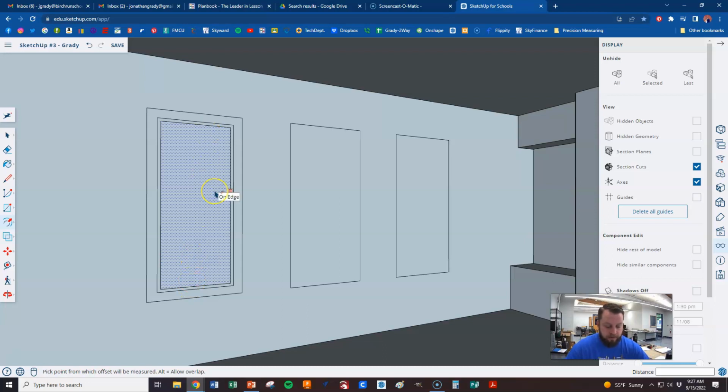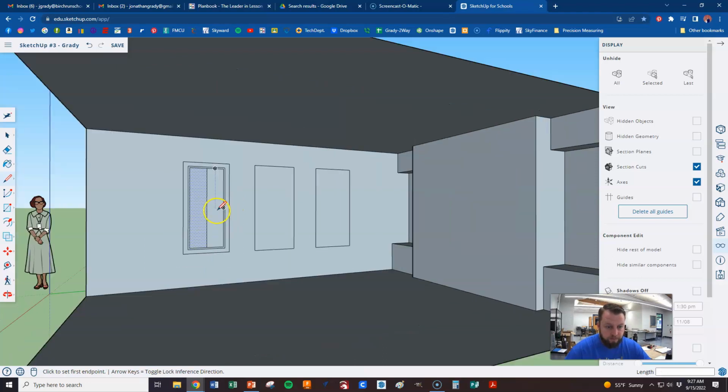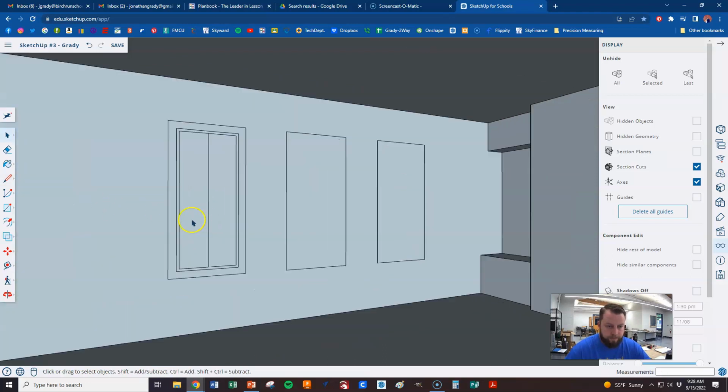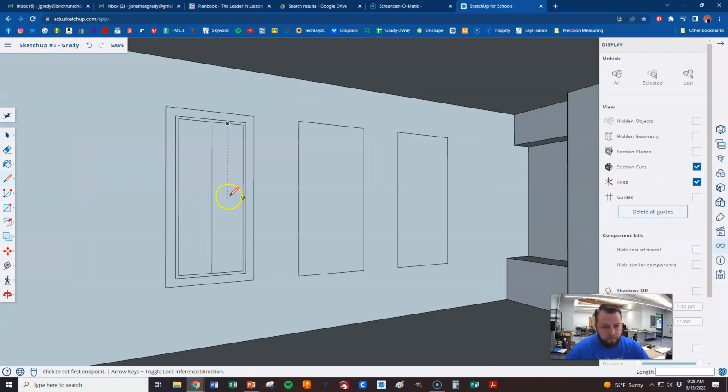And now we want to make a window pane here. And so we're going to go up here. I hit L for the line tool. Midpoint to midpoint on just this interior one. And midpoint to midpoint. So now I've got this nice square window here.